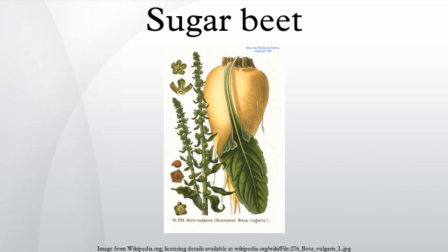Today, mechanical sowing, herbicide application for weed control, and mechanical harvesting have displaced this reliance on manual farm work. A root beater uses a series of blades to chop the leaf and crown from the root. The beet harvester lifts the root, and removes excess soil from the root in a single pass over the field. A modern harvester is typically able to cover 6 rows at the same time. The beets are dumped into trucks as the harvester rolls down a field, and then delivered to the factory. The conveyor then removes more soil.